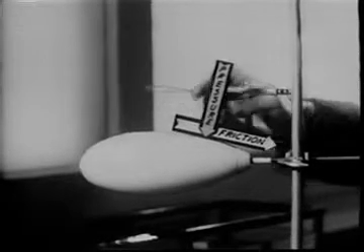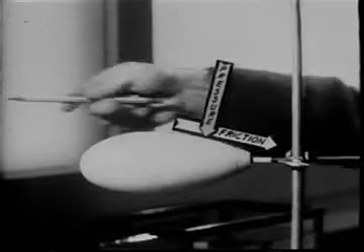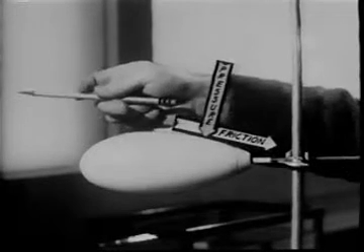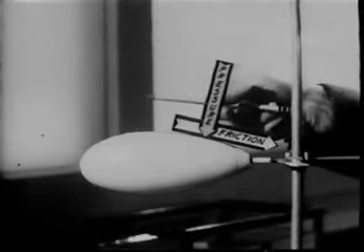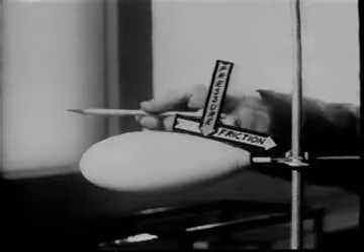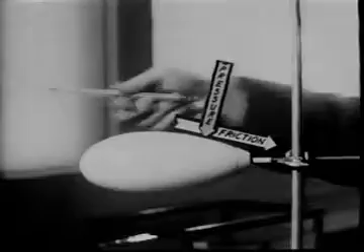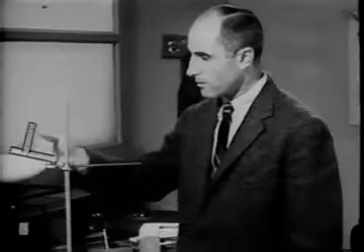Adding up all such components for all elements of the body's surface, we get two contributions to the total drag: pressure drag and friction drag. Friction drag is always present because all fluids have some viscosity, but the pressure drag may be either very large or it might be quite negligible.